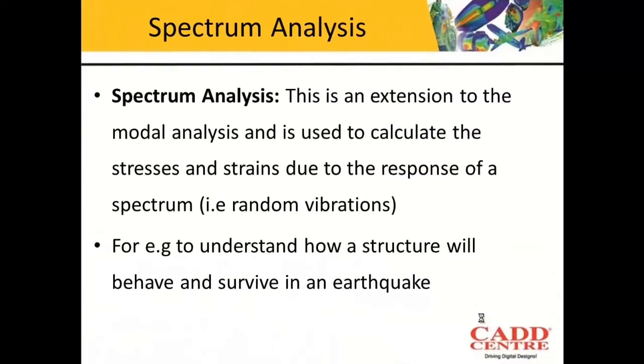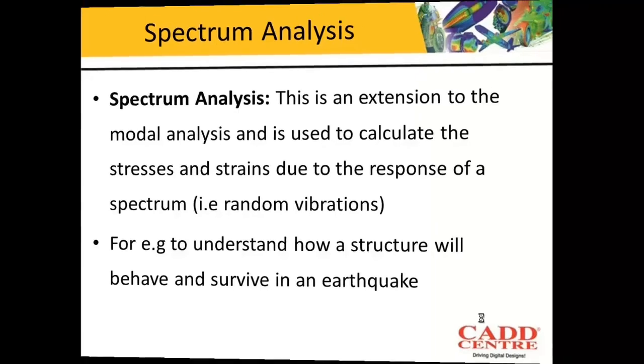Next, we will go to spectrum analysis. This type of analysis is an extension of the modal analysis, and it is used to calculate stresses and strains due to random vibration. The best example to understand what spectrum analysis is, is to study the behavior of a structure during an earthquake.